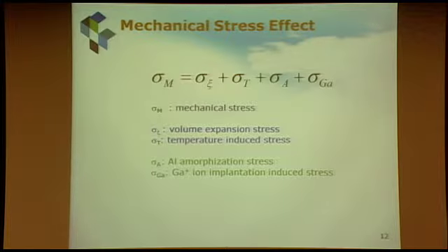And another thing we have done is look at the stress distribution, because during this anodization process, we have a few stress components. The first one is from aluminum to alumina, there is a volume expansion, a huge one actually. It generates quite high stress. Another one, there is a chemical reaction going on, so you get a temperature gradient, there is another stress.